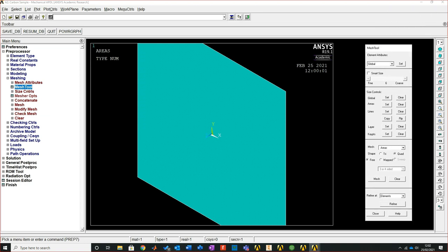And in this meshing tool, again, it looks really primitive. But what I'm going to do is use a smart size tool. Now I can use the automatic, and with the automatic it will probably just break it down into large base quads, so we'll end up with huge triangles on it. Now I'm going to make this semi-fine. So I've clicked onto smart size. I've dropped it down to 4. The 4 in this case is going to be quite refined.